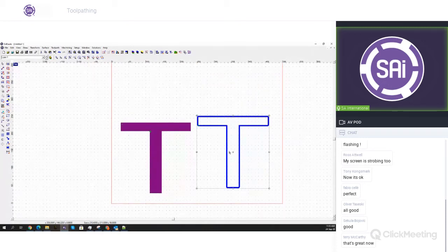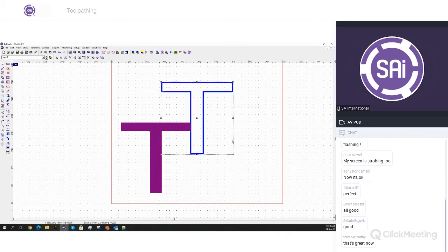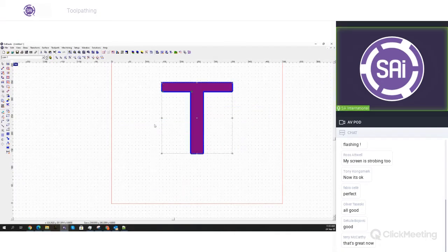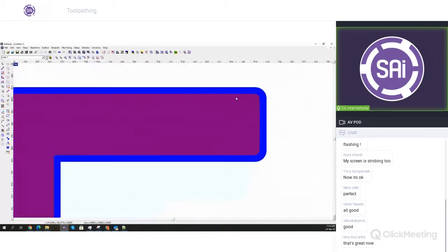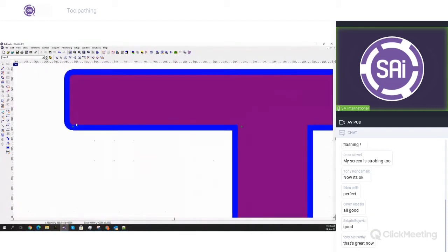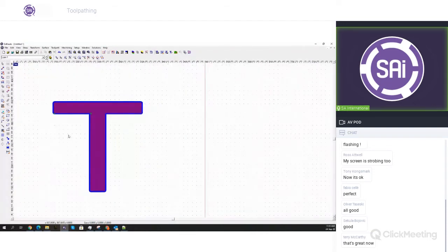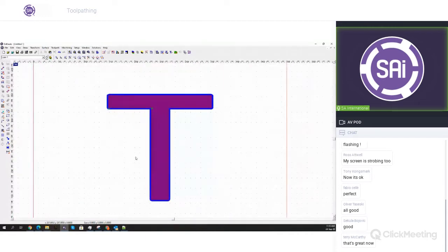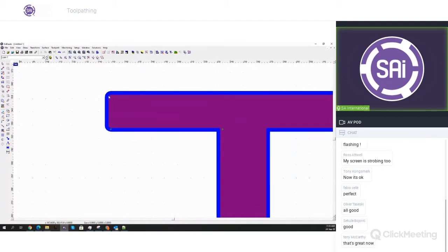So if we then visualize the toolpath, then this letter will be able to, let's just use Control-5 to center it to the plate. We'll be able to inlay these ones perfectly into each other. So if you check that inlay option, it'll tell EnRoute that it has to mind the tool diameter for both the inside and the outside corners for both the male and the female cut, so that they can be perfectly laid into each other.